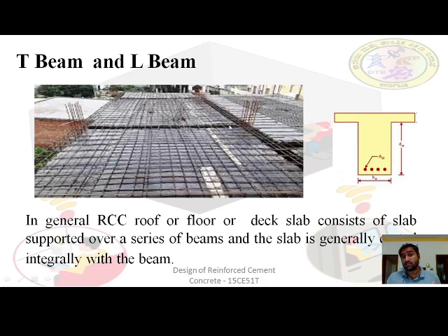From the geometrical point of view, we are not casting any T-shaped beam, or pouring any concrete in a T shape. It is the combined action of the slab and the beam. When the beam and slab are cast together, a new action is generated. That action I can consider as the T-beam action. So let us see the conditions, one by one.